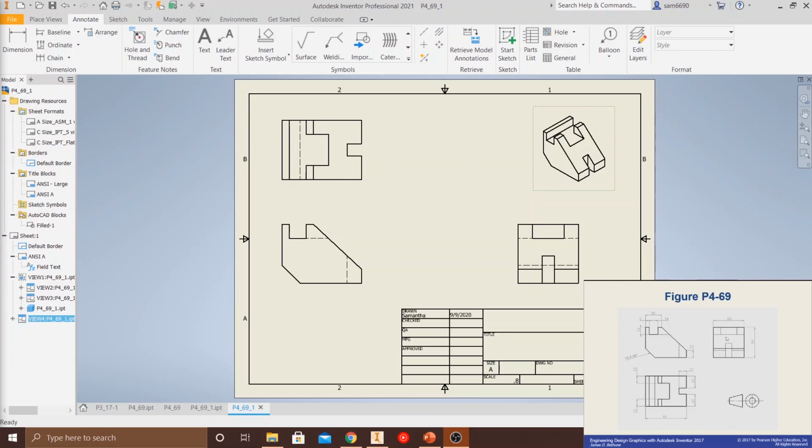So our right side view is going to look different, as you can see. Looking at this right side view, you see how in the left side view we had these dotted lines across. This is our hidden view, okay? These are the hidden lines. This is looking from the left side, and you can't see these normally. If you were looking at the left side, you would just see a rectangle with maybe some shading due to this chamfer right here.